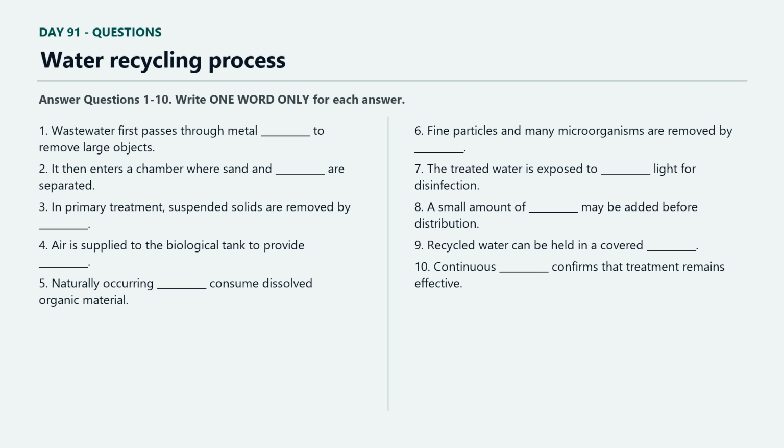The water enters an aeration tank containing a managed community of microorganisms. Blowers or mechanical devices transfer air into the liquid and keep the contents mixed. The purpose of this air supply is to provide oxygen for aerobic biological activity. The equipment also prevents the biological solids from settling too early. Supplying more air than necessary wastes electricity, while insufficient supply slows treatment and may create unpleasant conditions. Sensors help operators maintain an appropriate concentration under changing flow and temperature.